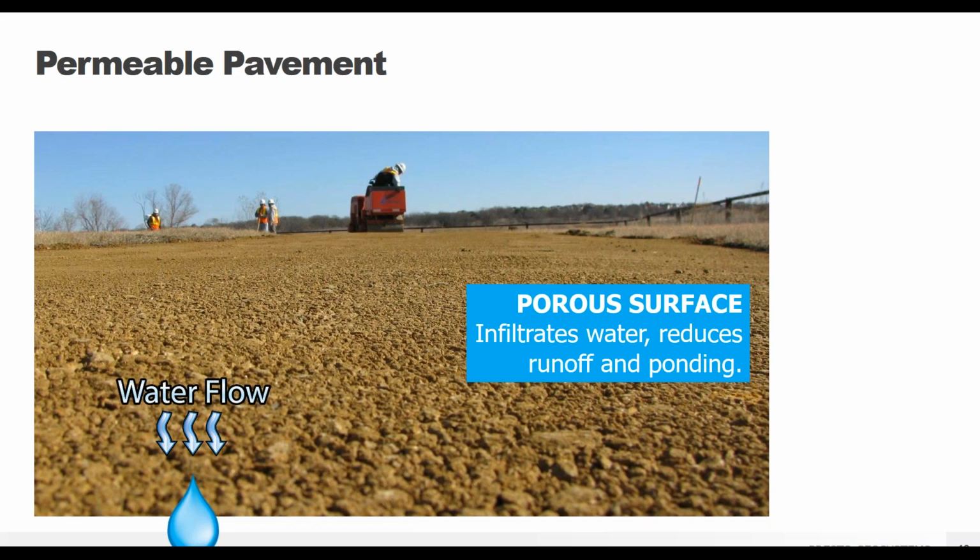So a general rule of thumb is that 3/4 inch open graded aggregate has a void space of around 35 to 40%. So imagine how much water you could store within that void space to reduce stormwater runoff and ultimately have the ability to reduce stormwater pond volume and land requirements. So something that we're able to help with if you do have questions.